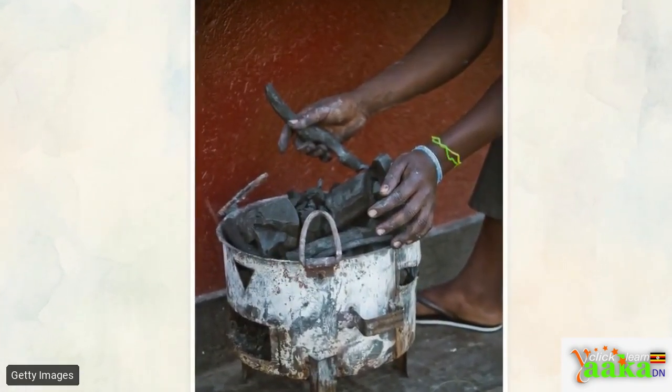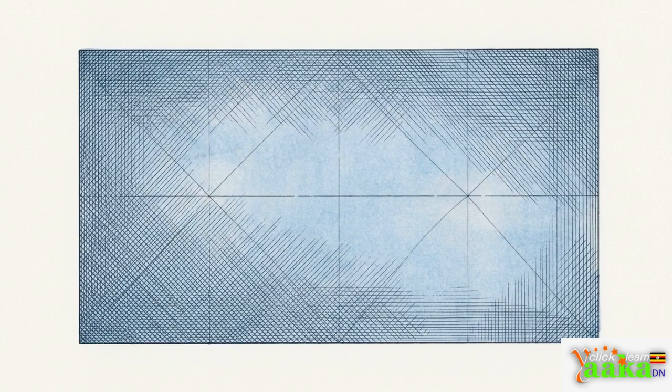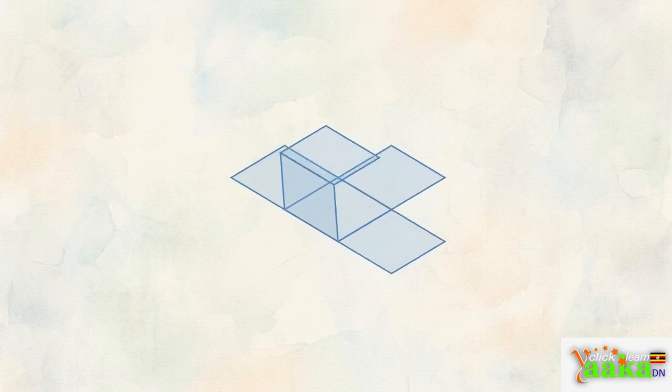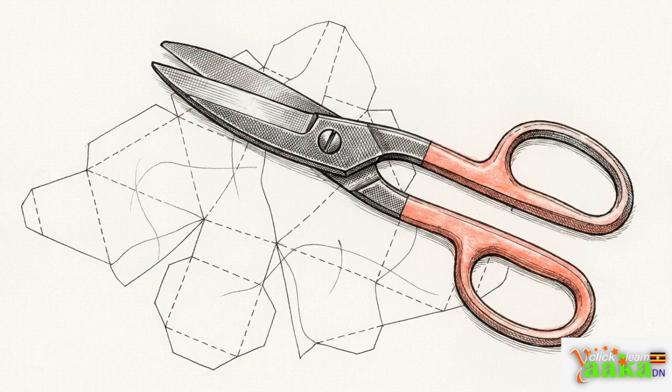Look closely at this locally fabricated metal stove. Before it took this cylindrical shape, it began as a flat sheet of metal. Converting that flat sheet into a functional 3D object requires surface development. In engineering, development is the exact method of stretching out or unfolding the entire surface of a three-dimensional solid onto a flat two-dimensional plane so it can be accurately cut and formed.